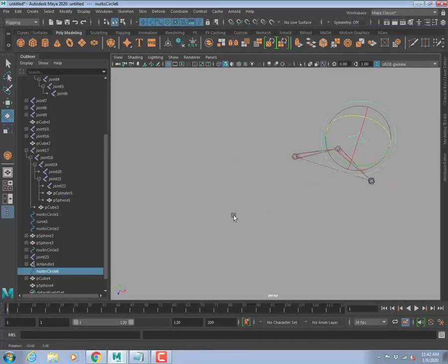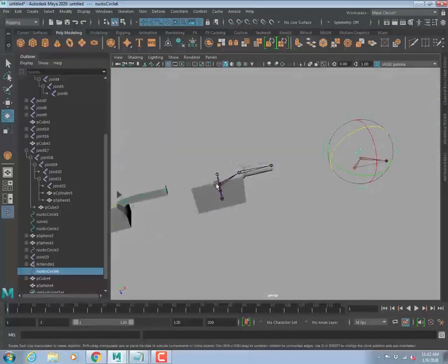What if I'm making a model of an RC controller? When I move this button, that object should move up. For example, I move this down, it rotates up. So here I'm using translate, there I'm using rotation, so different attributes. For example, when I move this, that one should be scaled up. That is where we use Set Driven Key.